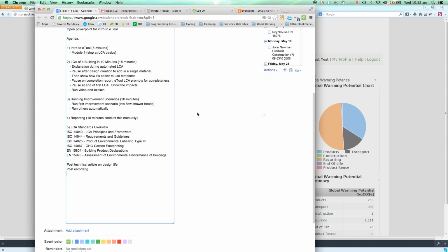Yeah, no, absolutely. So the way you have to deal with it in the current EN 15978 standards, you have to assume current recycling or end of life scenarios. Like you have to assume what's happening today will happen in 50 years, which I think is a pretty pessimistic take on it. Conservative. Yeah, absolutely. But that's the best you can do, isn't it? Yeah. I think from that point of view, if you're claiming a credit, you're probably claiming a pessimistic one.